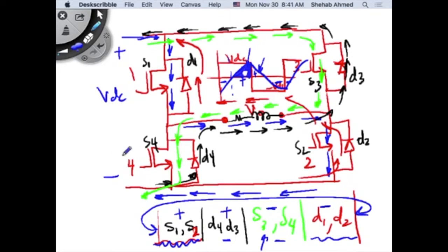But what we want to get to is something that looks like a sine wave, and we will be switching multiple times per period and creating something very close to a sine wave. Sure, in that case, if we want to maintain this ripple low, the inductance is something that we can add to maintain lower ripple, yes. I don't know if I answered your question.